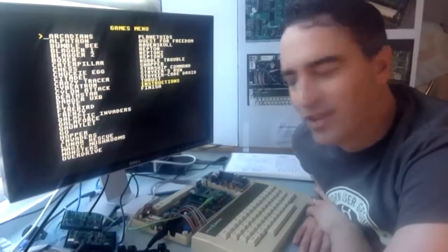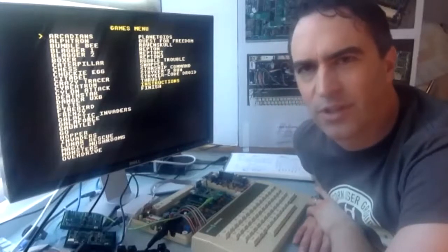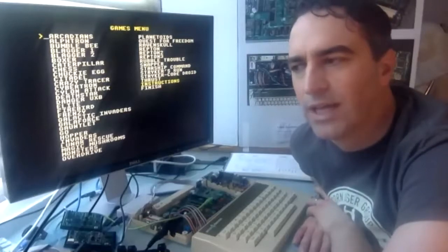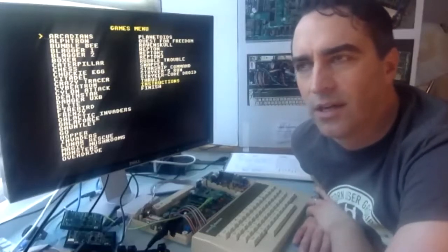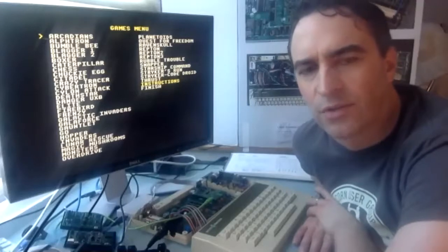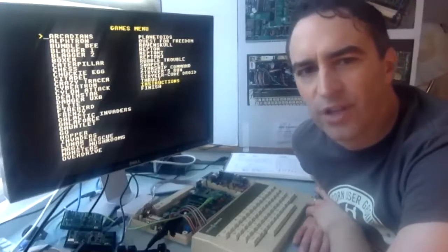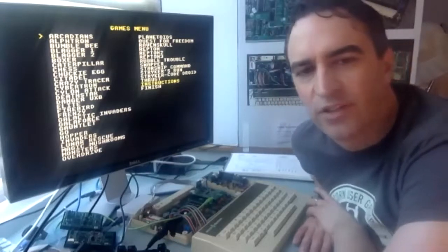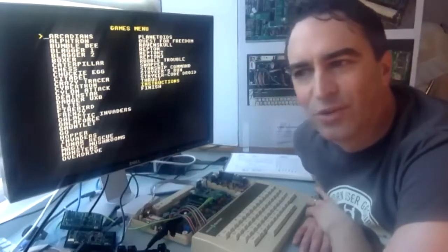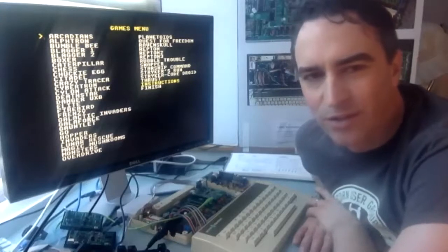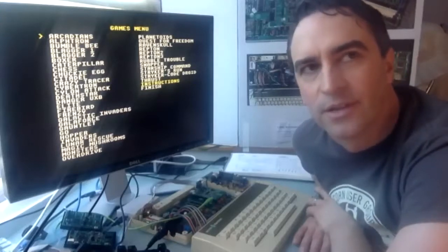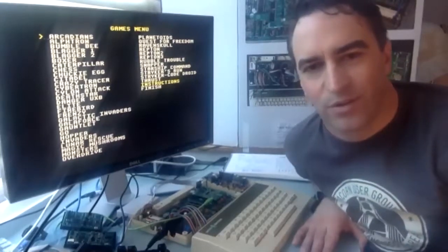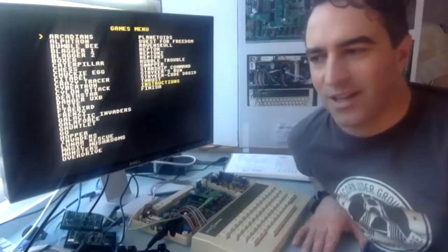The block RAM inside the FPGA is kind of limited. I think there's something like 42K, and obviously I'm using 32 for the processor's memory. There's some for mode 7, there's something for the video. So there's not a lot left. But we have this SDRAM, and like I said, you can access it in 60 nanoseconds, which means up to about 16 megahertz access, so I can run several 6502s at full speed. So I'm going to try that.